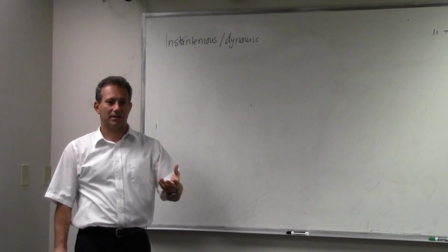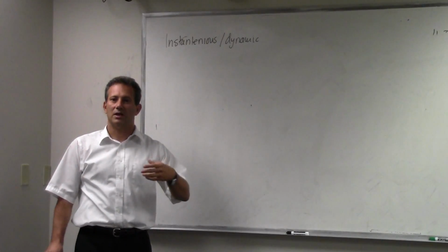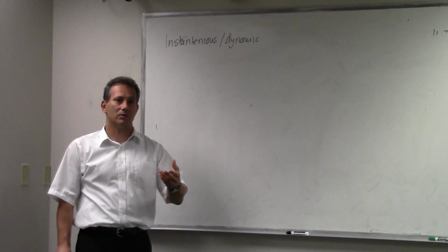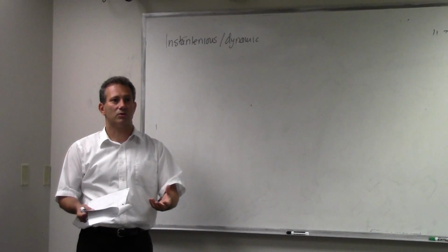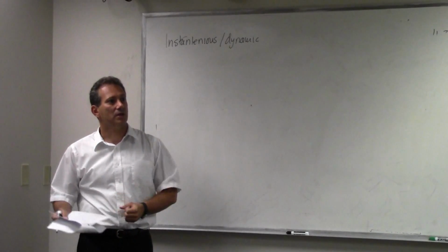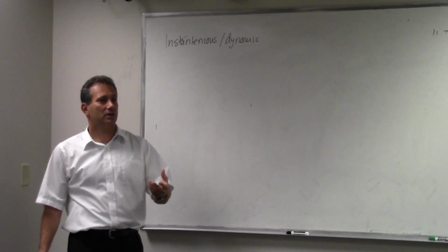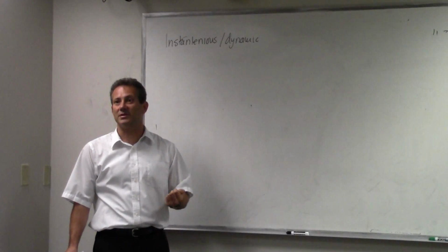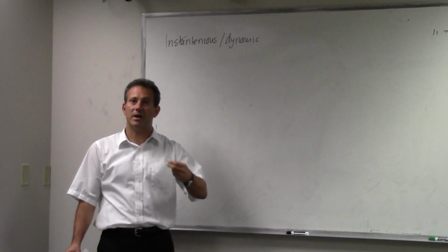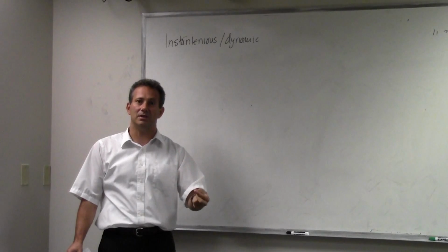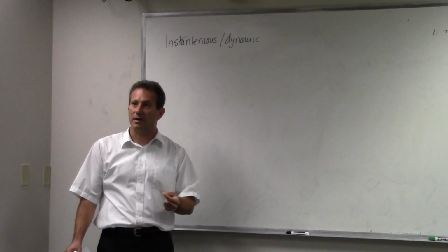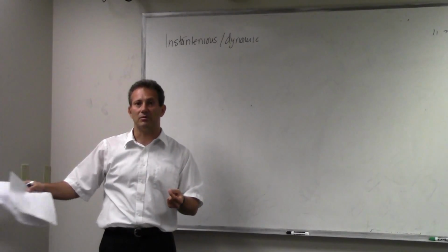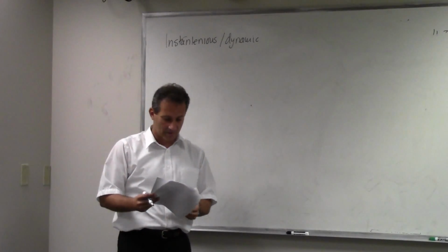Now, in a more practical scenario relative to this course, if you have an RLC circuit, the output of that circuit will depend on the energy currently stored in the circuit, and also on the input presented to the circuit. In general, these kinds of systems that have what we call memory are called dynamic systems, right? They are systems with memory. The output at any given time t depends on the input at that time, but also on the past trajectory of the system, what has happened to the system prior to that time t.